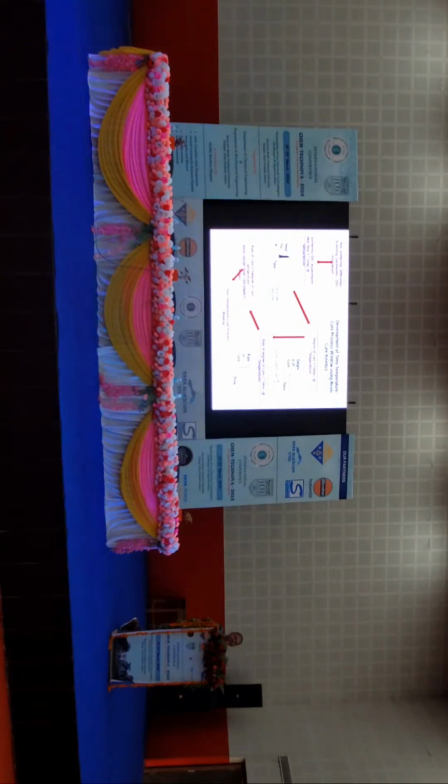If I make a thick-sectioned composite product using a ramp, in non-isothermal mode of curing, what will happen? What will the temperature profile through the thickness be? It always varies, right? Because the fiber will have certain thermal resistance. So obviously you will not have a uniform temperature profile along the through-thickness direction. If the temperature profile is not uniform, the curing also will not be uniform.